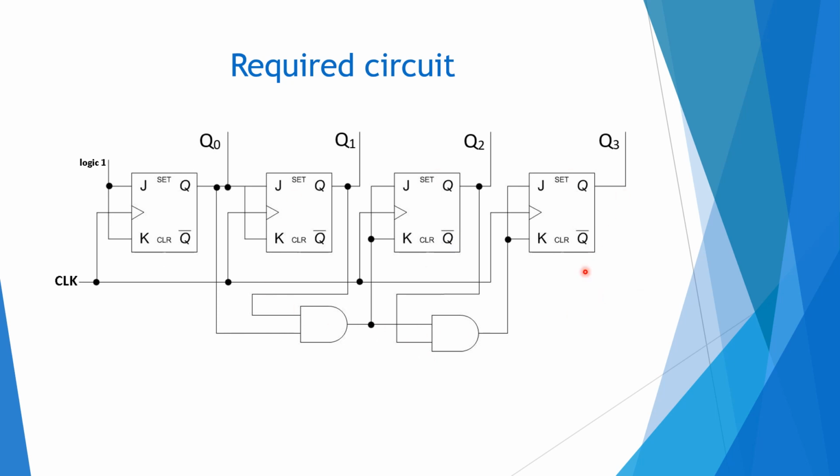So if we follow the same procedure, we can design any type of counter. And here you can see the clock is given to all the flip-flops simultaneously. So that's why it is a synchronous counter, a synchronous mode 16 counter.